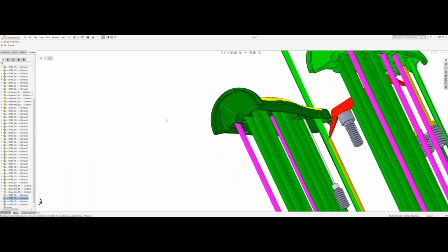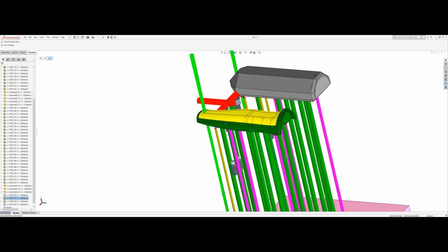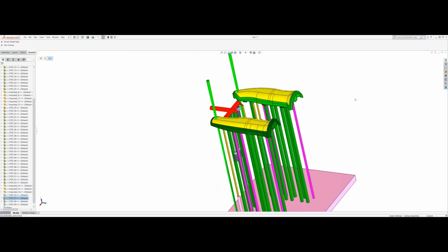Next question, did you need to marry cavity 1 sub to cavity 1 overmold, cavity 2 to cavity 2, etc.? Well, in this case, this was low volume. So we only had single cavity. So the substrate tool was just a single cavity, and they matched up. So yeah, there was no concern of that. In a production setting where if you had multi-cavity, say it was a 2+2 or something like that, then yeah, you would probably want to match those up for the run.